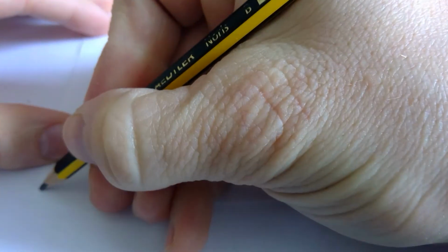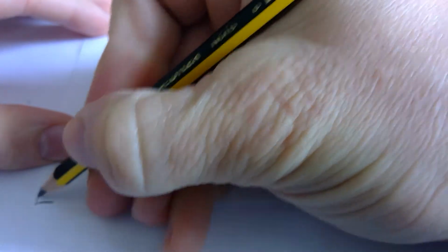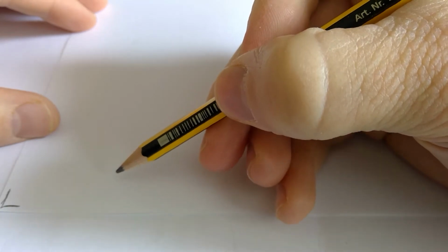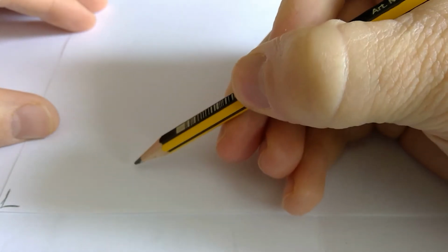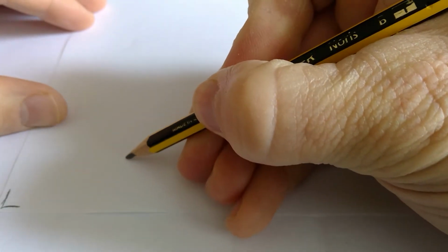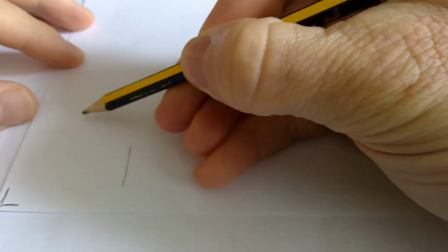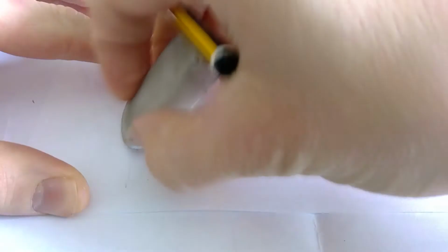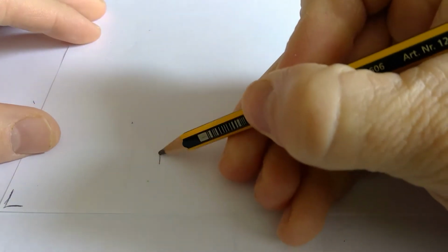Remember what we said before, when you're drawing these details, start where you think the builder would start. Start in a place as if you're building the house. There's the bottom corner of my page. I'll start fairly low and to the left, just to make sure we always have space. When you're drawing a timber frame wall, I would always start with the timber frame panel first, the inner leaf, because the inner leaf is actually what they put in place first. So a timber frame panel, make sure you leave a bit of space over here for the eaves detail of the roof. I'm going to make sure I have an extra bit of space.